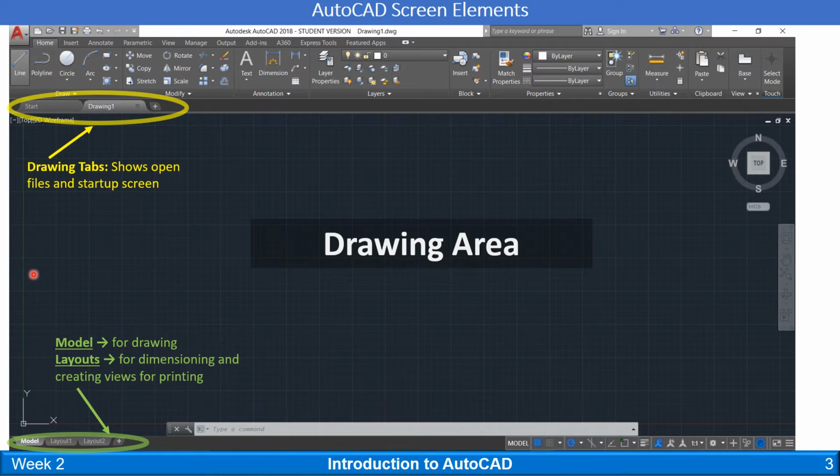Down at the bottom, there's a few tabs too. The Model tab, this first one, is where you want to do all of your drawing. So that's what we see right now with the black background. The layouts over here, we'll get into that when we start doing dimensioning and looking at the different orthographic views of things. And this is for when you want to print it out onto a piece of paper. So whether you're using a giant plotter or just your regular old computer printer, this is where we're going to format it and scale everything so that it fits correctly onto a piece of paper with title blocks and stuff like that.